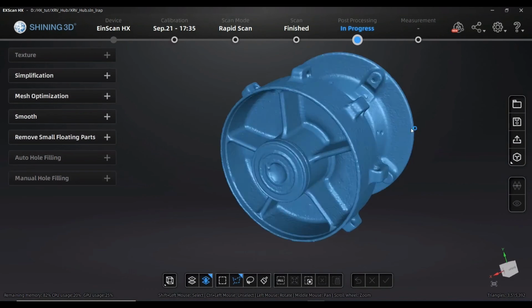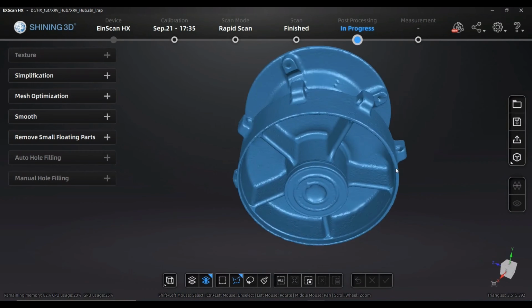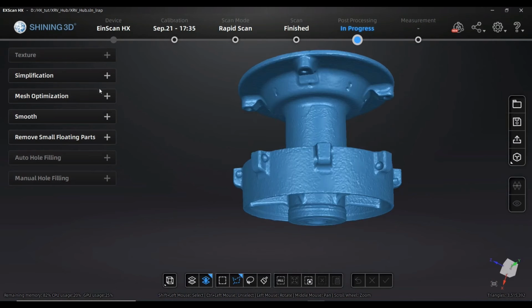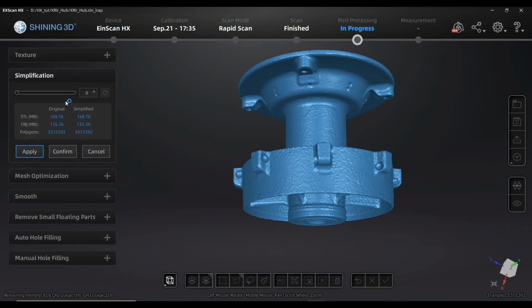What next? I just used quite a high resolution to go to the mesh. Why did I do that? Because a simplification is possible here as well, and there seems to be some difference. That means simplifying here, and I will be able, by pulling the bar, to see how much I will come down in size. For example, I can see here I'm at this moment in a simplification that will create an STL file with 104 megabytes. That's already capable for many of the CAD softwares.